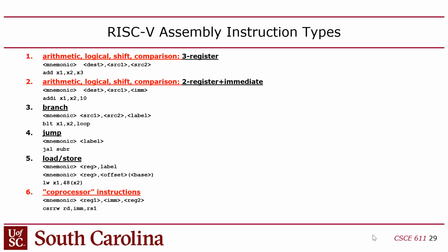But that's not very useful if you're designing the hardware, because in the hardware, you just give it a base register, like a pointer. You guys know about pointers, right? Like in C, pointers. So a pointer is an unsigned integer that's a memory address. And to use the pointer, you have to dereference it, meaning that you take that address and you go to the corresponding location in memory, which then you can read or write. That's called a dereferencing operation. So the way the hardware instructions work is through a dereferencing operation.